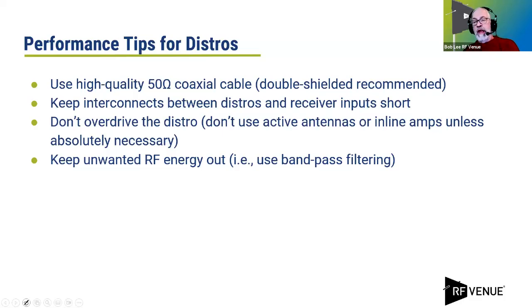We'll also have to deal with 5G phones, like my T-Mobile phone here. That's a culprit there. I can often see it on my spectrum analyzer. It's like, oh, look at that, around 620 megahertz. There's all this noise going on, and that's from my phone. So even though that's outside of our band, it can intermodulate with other signals and produce noise that's in our area of the RF spectrum.